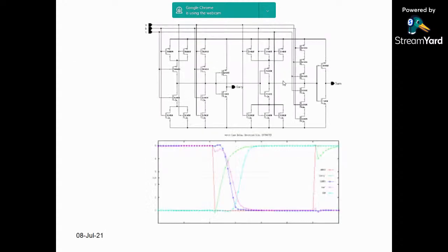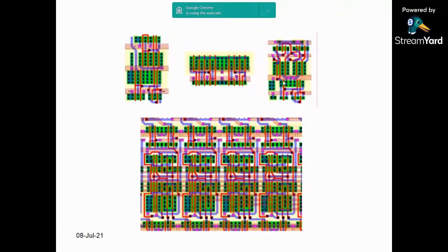I just want to show you a glimpse. For example, I want to design this particular circuit. This circuit will be drawn by the design engineer with everything characterized, drawing the layout. This is not like a PCB layout. This is actually a layout drawn for the particular circuit using the layers. They use the tool and draw the N diffusion layer, P diffusion layer, wherever the transistor is. This is the layout of gates.